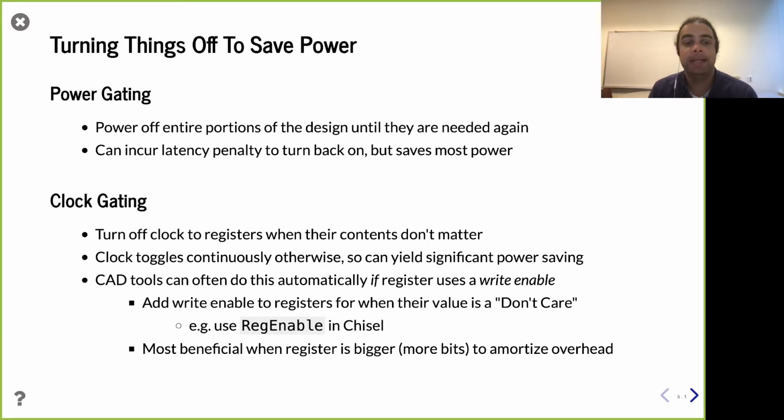And so, yeah, in order to have your registers not do something silly when the clock is gated, there's a little bit of extra circuitry put in there, but it's going to save quite a bit of power, right? And what's interesting about clock gating is this was something that was really, really cool technology in the late 90s, early 2000s. And for the last 10, 15 years, it's something that CAD tools do automatically, right? So in the spirit of make the tools do the work, this is definitely something tools do well.